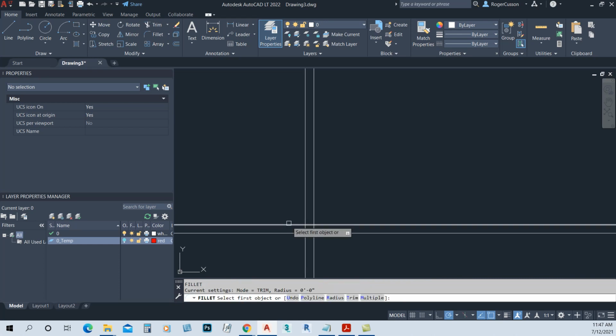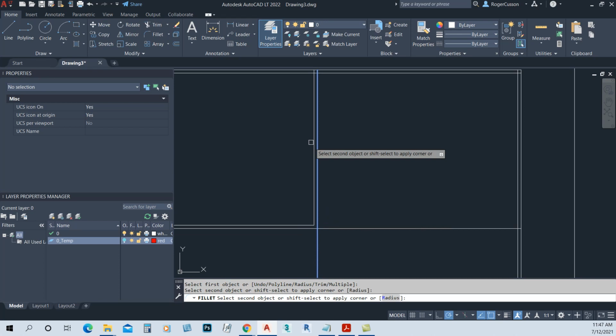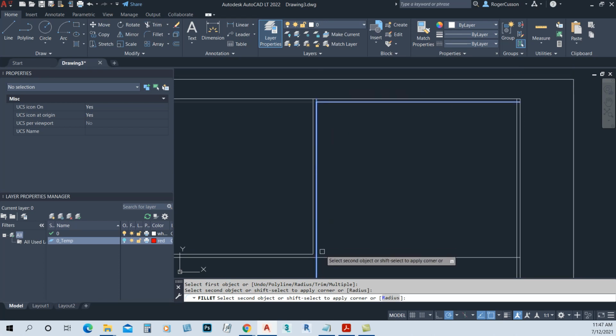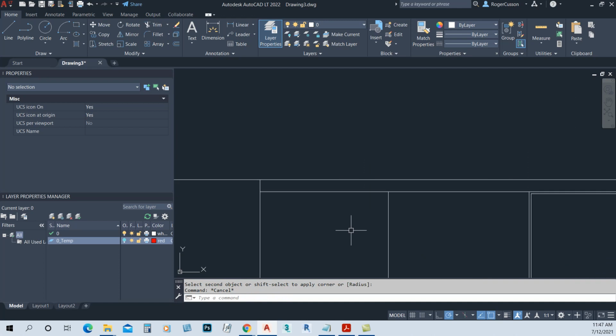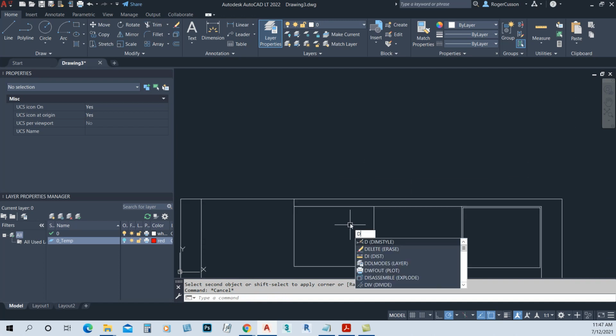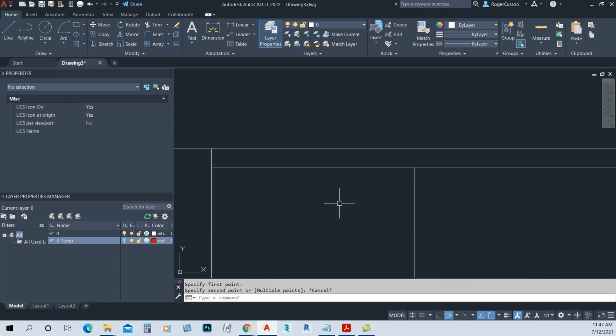It's a little bit of a mess, so I better start using Fillet to clean things up, otherwise I won't know what I'm doing very soon. So let's do this. Okay, so this will be my stove. Let's check with the distance command, DI. This distance, 2'7", that's good.